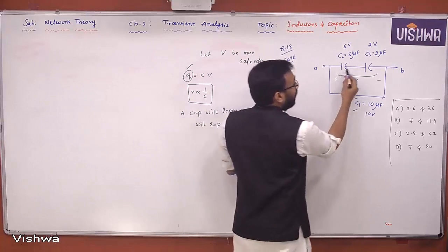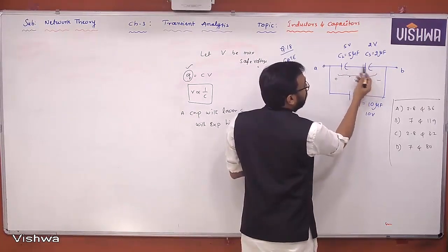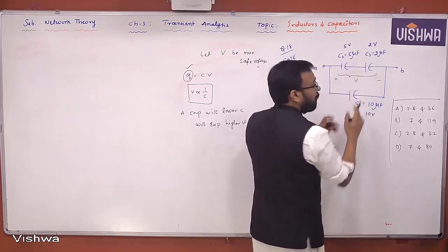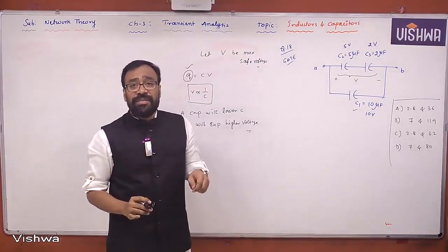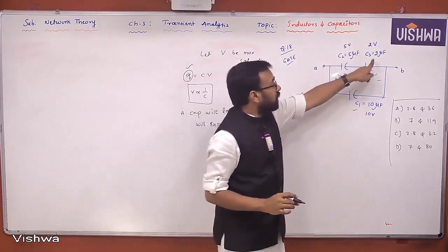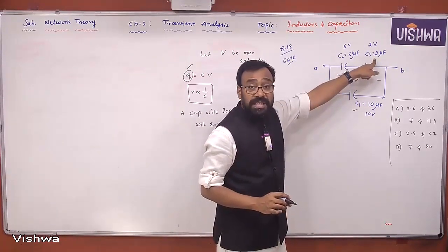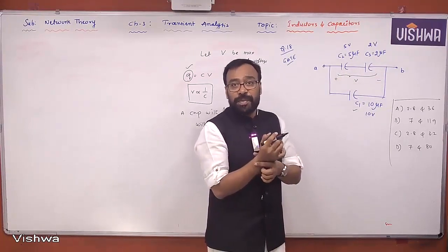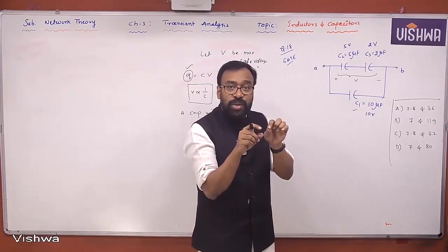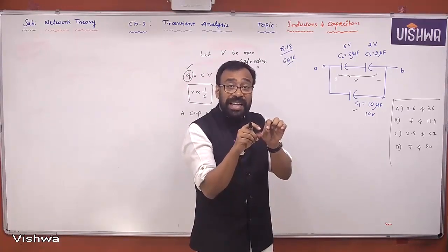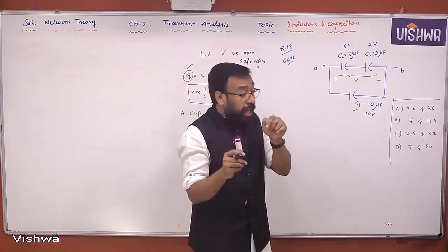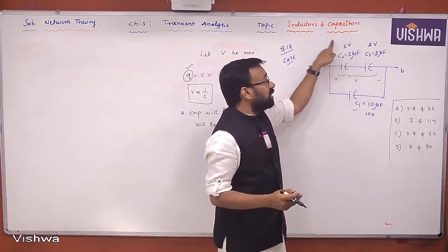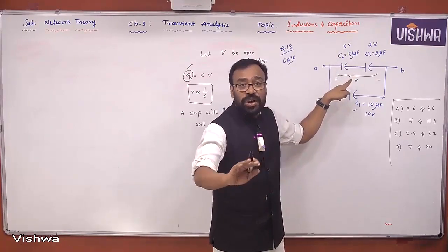Okay, so who actually has a problem now in this problem, C2 5 microfarad, C3 2 microfarad, when the two capacitors are connected in series? A capacitor which offers lower capacitance. Yes or no, all of you, okay? Now the 2 microfarad capacitor has some problem. If you design that maximum safe voltage keeping in mind this particular capacitance, then obviously the other is also taken into consideration or not?